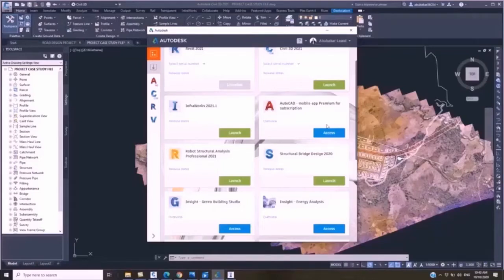Doing that, we should be able to extract our spot height elevation for the site condition using the point cloud conversion procedure, and also using the digital elevation model and digital terrain model integrations in Infraworks to get the exact topo of the environment. Let me quickly show how we coordinate that in Infraworks.